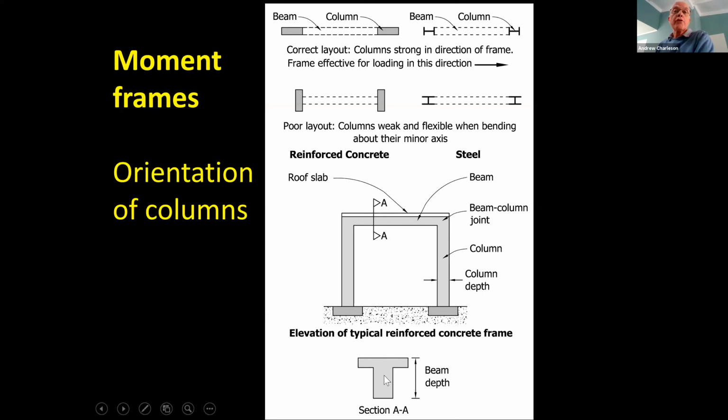And this would be a section through the beam. The beam depth would be considered the depth of the beam plus the topping of the floor slab. That would be the overall depth that you would provide in your design.